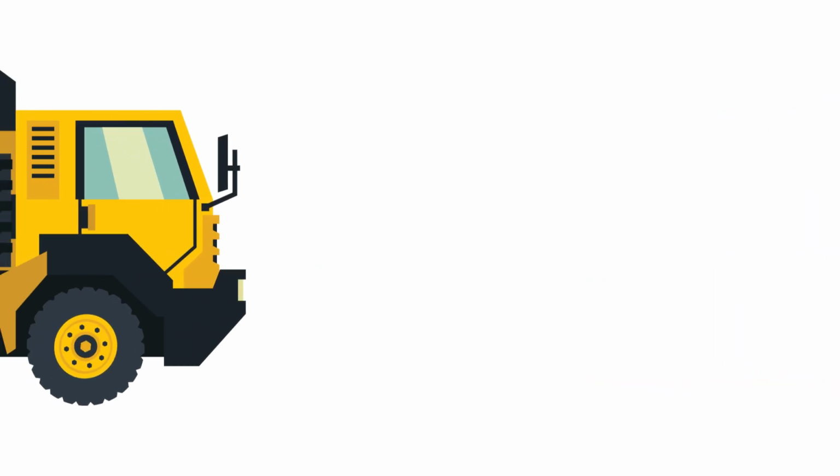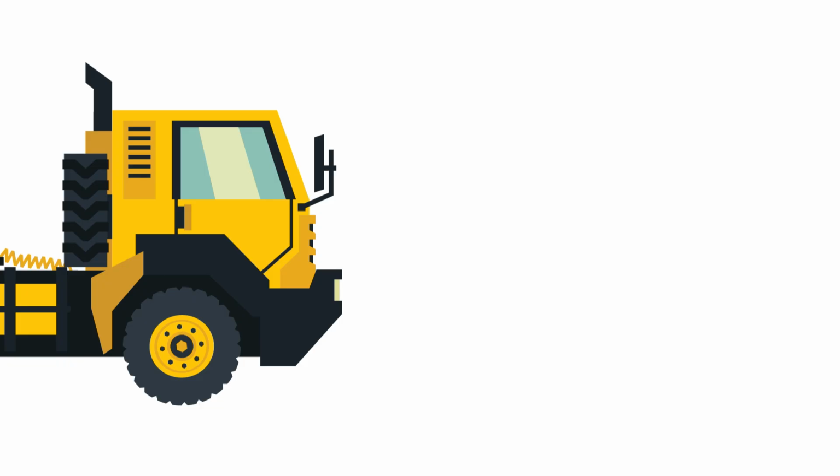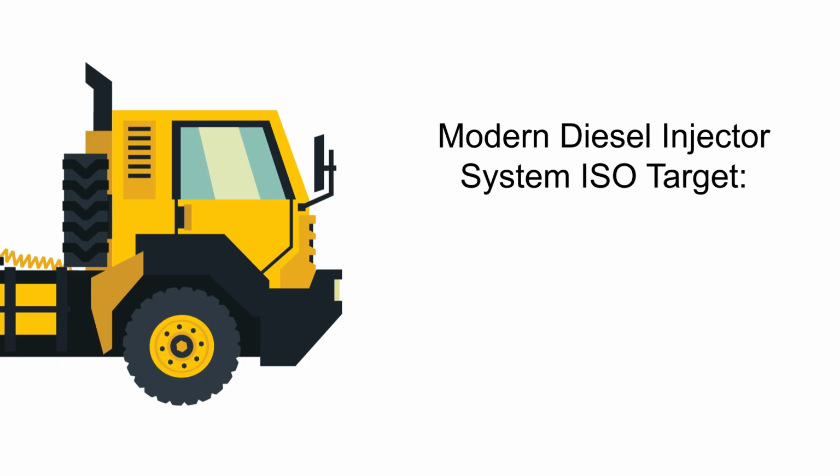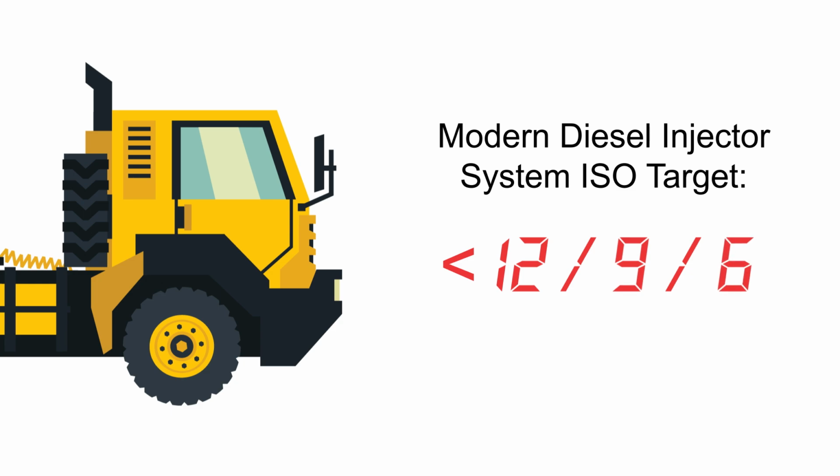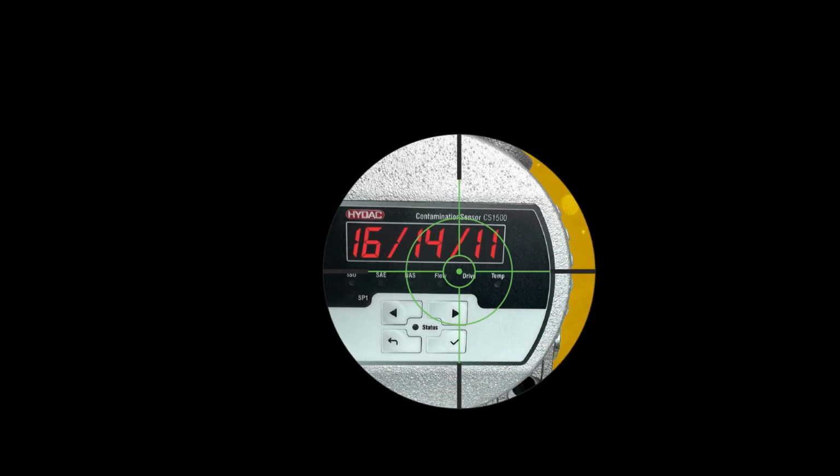Diesel systems are much more sensitive to solid contamination. The current standard for a modern diesel injector system is an ISO target below 12/9/6. Once you know the ISO target for your equipment, it's extremely important to stick to that target.